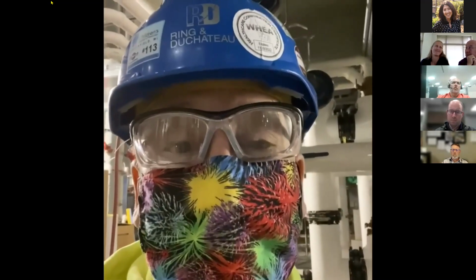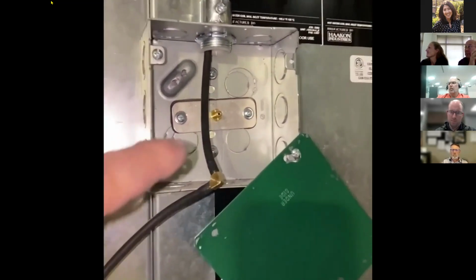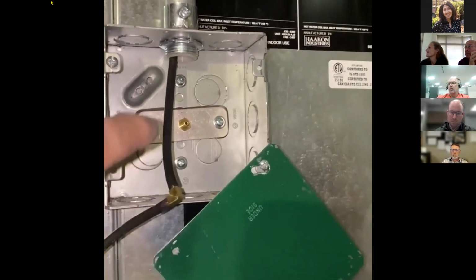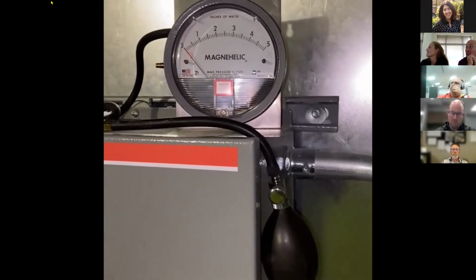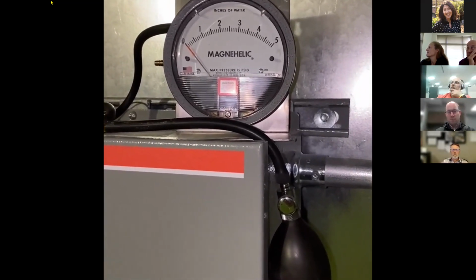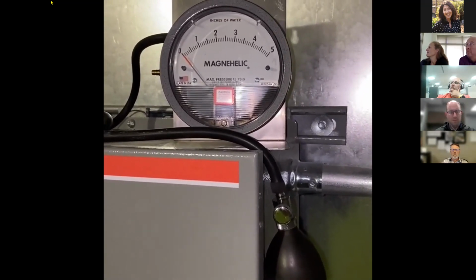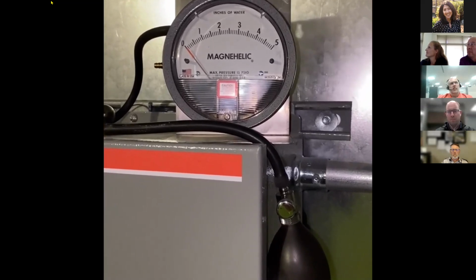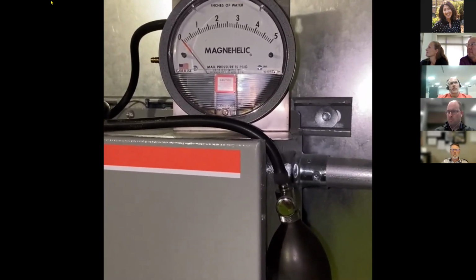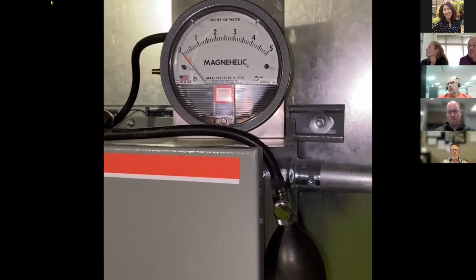All sorts of excitement on the job site. Not that it's overly important, but we worked to disconnect that key from there, then connected our poly tubing to our little test assembly with the test bulb and the Magnehelic. And no one's really mentioned that we're giant advocates of just using a Magnehelic versus a digital gauge. Digital gauges oftentimes have a little buffer in them, so they're not completely instantaneous, and what's 0.05 inches amongst friends.